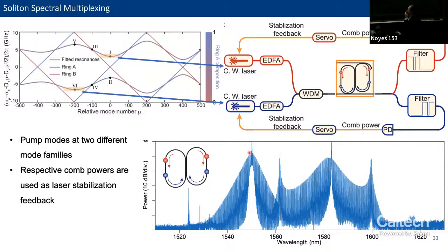You can see we have two sets of optical frequency combs simultaneously generated from this resonator. Each of these soliton frequency combs features the well-known hyperbolic secant squared envelope at two distinct wavelengths. And the position of those two wavelengths can be arbitrarily designed by changing the length ratio, or the recurrence period, of the two resonators.